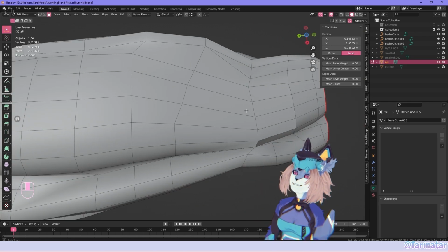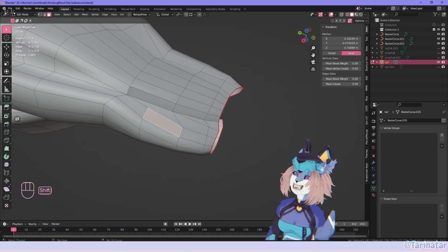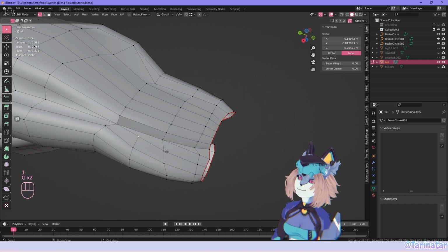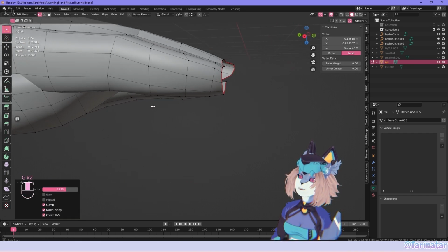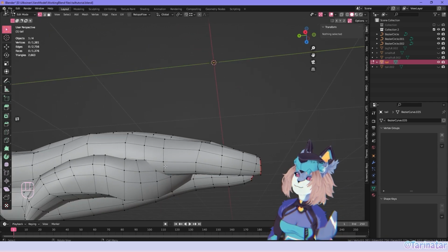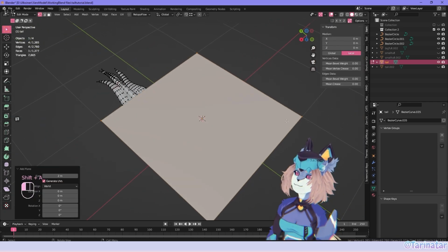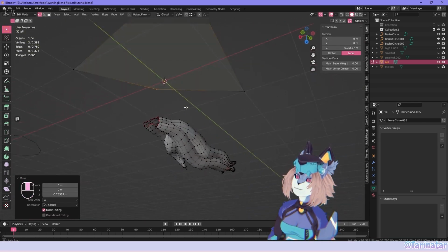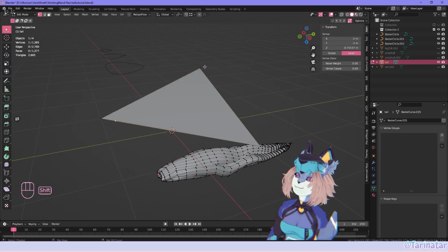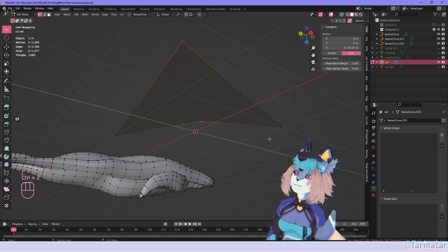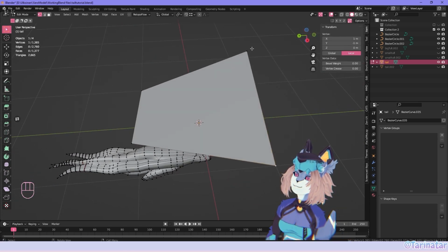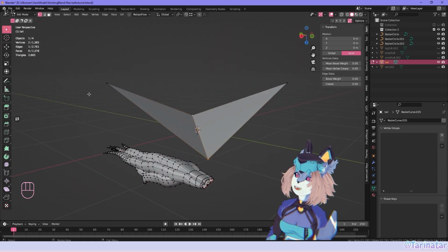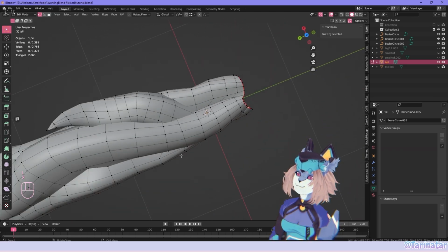Triangles are okay, they're not bad per se, but n-gons are the worst. Do not have n-gons in there. And why is that? The game engine or whatever 3D program is actually considering faces like this with 4 parts like a triangle. This is one face that is shaped this way. It draws it like, this time it decided the triangle goes like here. If we want this to be like a downwards V-shape, join these, and now Blender changes which way it considers the triangles to be. Basics. That's why triangles are fine.